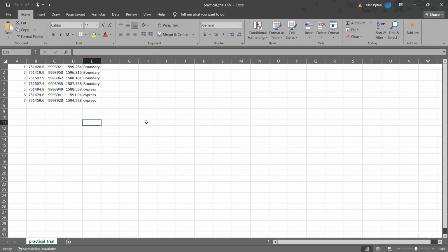The next thing is you need to close this data, and for that you will need to write the format somewhere. For us, we have the point ID, eastings, northings, elevation, and description. Then close it, because AutoCAD will not be able to read it when it's open. So I'm proceeding to close it.